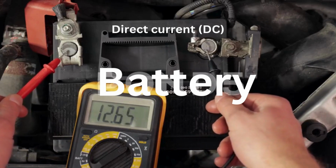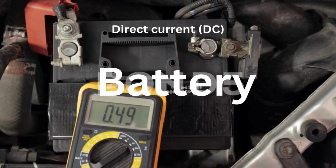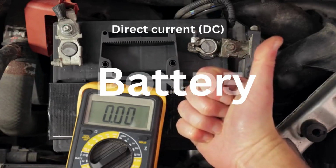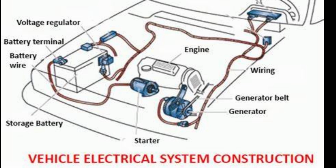Charging the battery. Once the AC current is rectified into DC and regulated to the appropriate voltage, it is sent to the battery for charging. The battery acts as a reservoir of electrical energy for the vehicle's electrical system and provides power during startup and when the engine is not running.